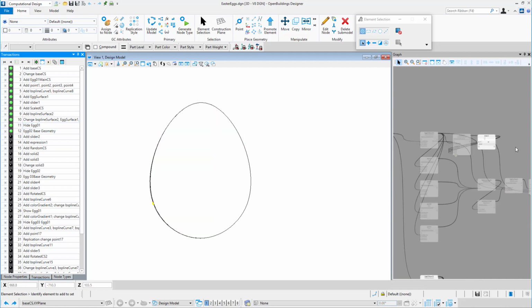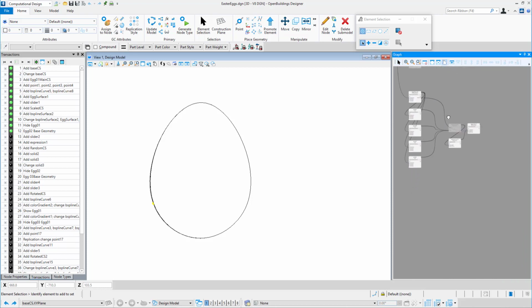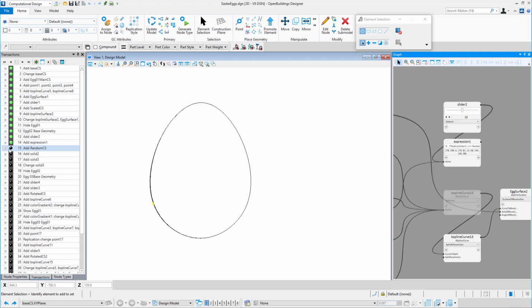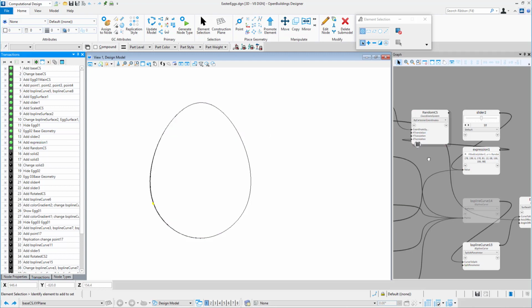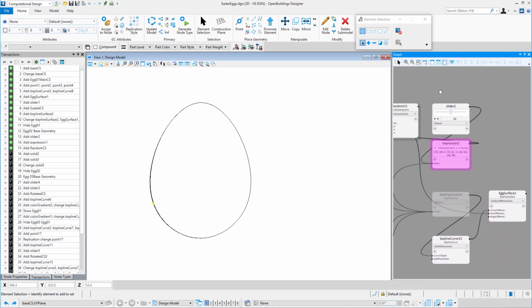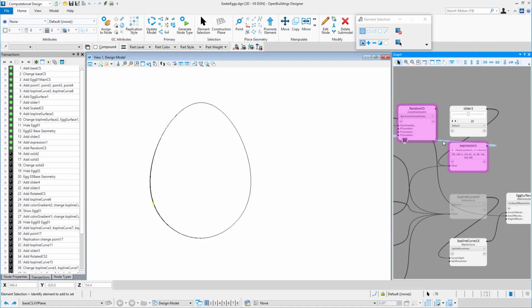We will repeat first few steps to create main geometry. In this example, we will cut our geometry with random planes. To do that, we will create coordinate system by Cartesian coordinate techniques, but in Z translation, we will create a list of random values. We can directly put the value in the Z translation input, or first, what I recommend, in expression node to check if function works correctly and then connect it with the Z translation input.